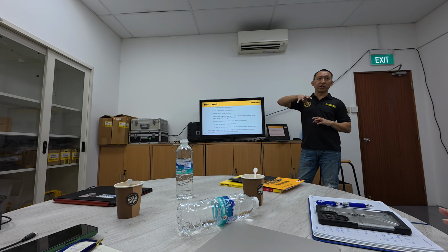That's not the way. And there's no safety, because you whack, you might damage the tool, or the hammer flies out and hits someone. It's not safe at all. It's not accurate. You might whack at different angles. You don't know how much force you are using. It's inconsistent, you have no control. No training, no competency, and no quality. So this is what happens when there's uncontrolled bolting.